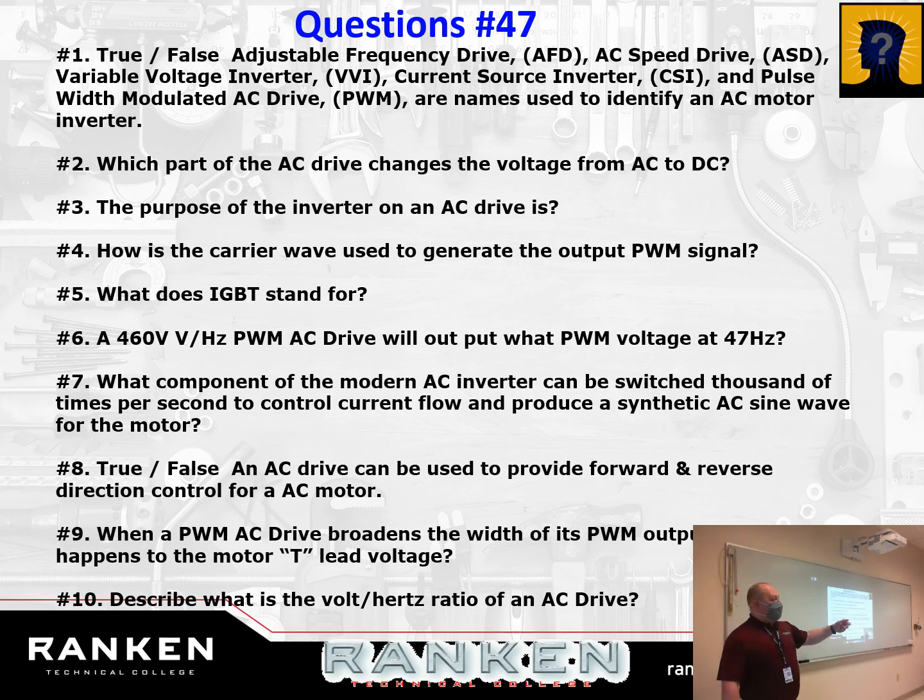And then there's a certain point where the frequency is so low that the voltage is so low that the motor won't operate. If you go down to 1 or 2 hertz, there's hardly any voltage to actually operate the motor. It can't produce torque. There's not enough field to do it. So it will fall on its face down low, and it will hit a tabletop, a ceiling on the voltage output. But in between, you've got a pretty constant ratio that most drives operate at.